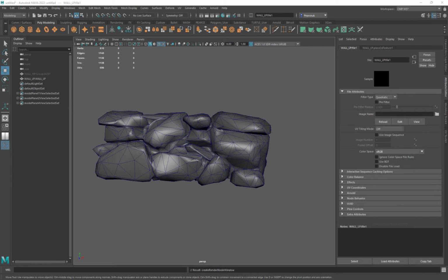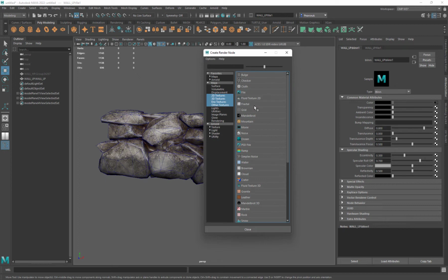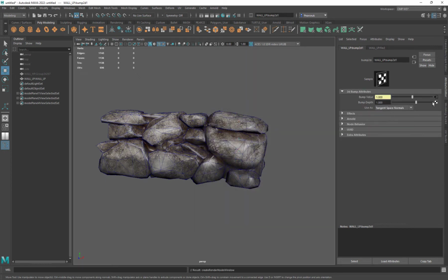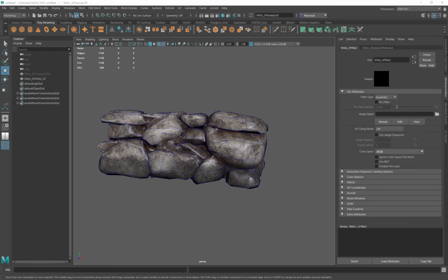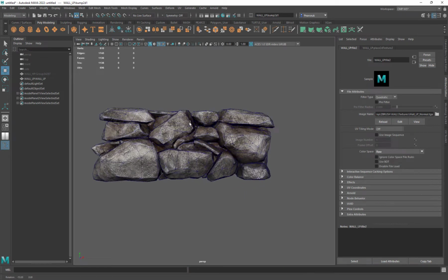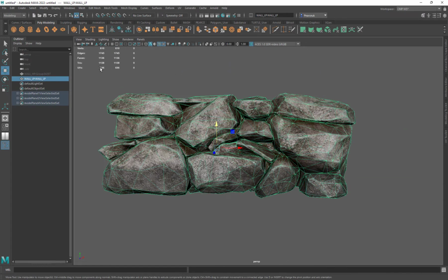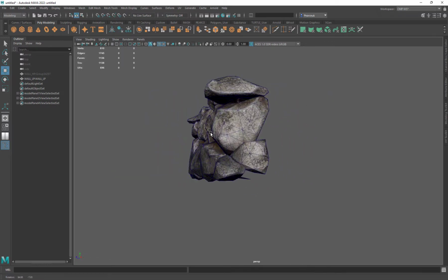Desktop. Zbrush wall. Textures. Color. Okay, so now I've got this in. And yeah, let's throw the normal map on as well. Tangent space normals. Normal, and then make sure that's set to raw if I'm using it inside engine. So okay, we've got this, and that's our kind of low poly. It's only 1,000 tris, which isn't too bad at all for something as dense as this.